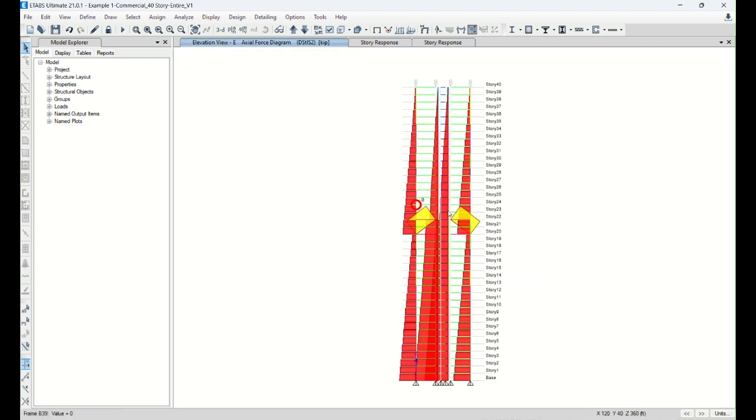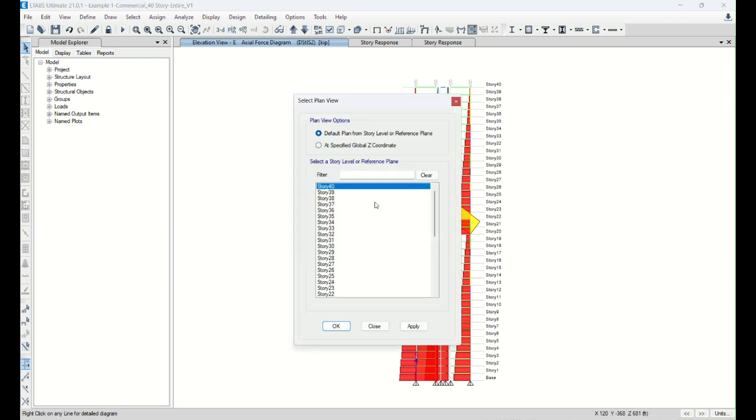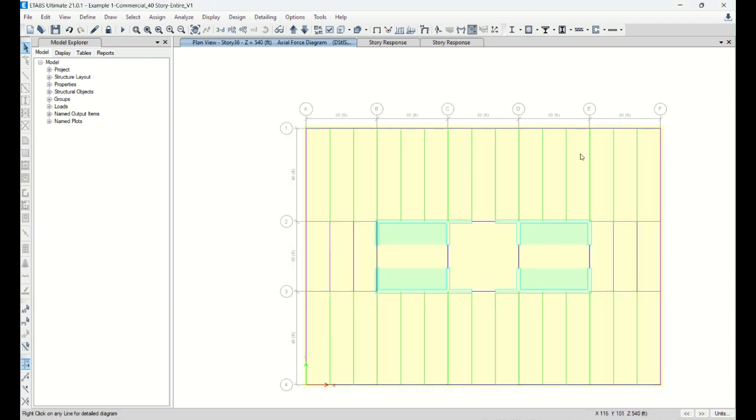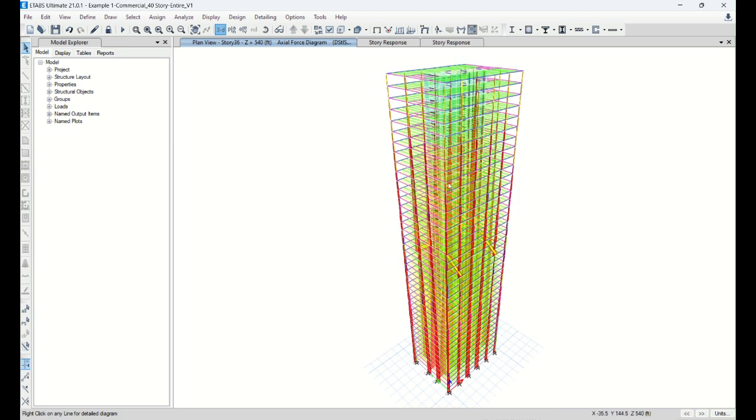So I think what you need to do is just look at your plan and choose the line of outrigger truss you want to add. Basically, at the exterior column, you put the truss in order to tie the column to the concrete shear wall. All right, so I think you can manipulate it and you may have to consider or continue.